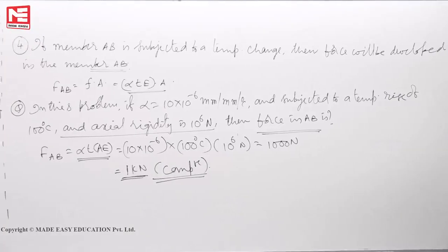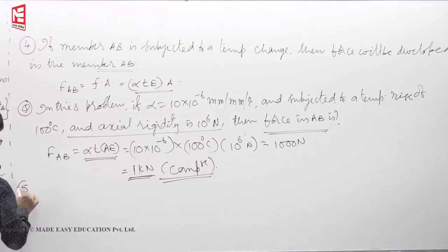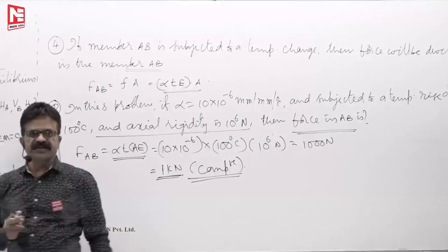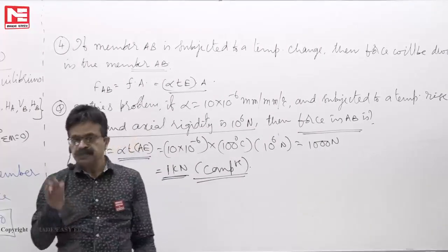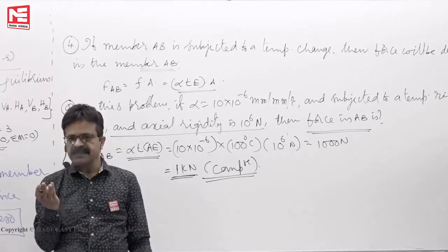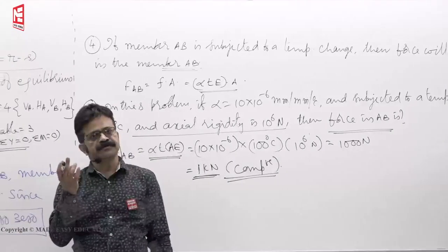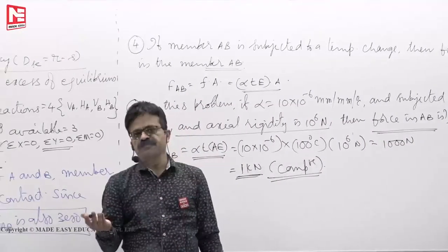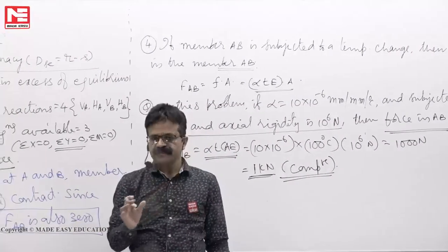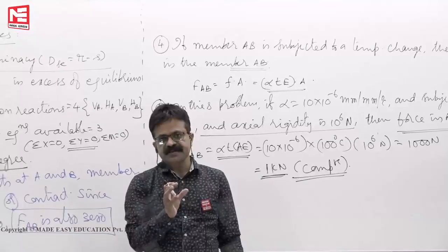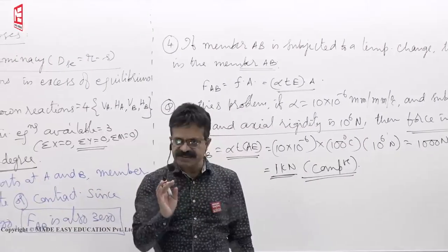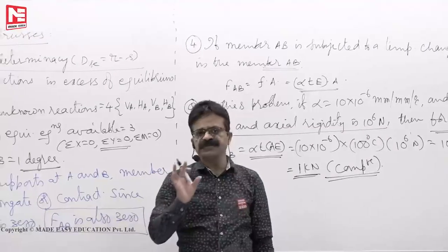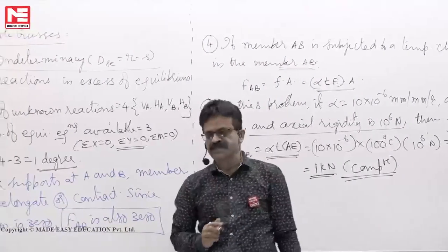So now the fifth conclusion we can write from this one. In any statically indeterminate structure, due to temperature change, sinking of support, yielding of support, fabrication errors, these four actions may produce some forces in the structure or may develop stresses in some part of the structure or entire structure, depending on the configuration of the structure and the configuration of the reaction supports.